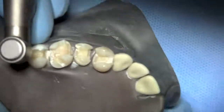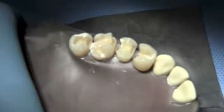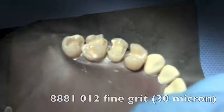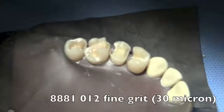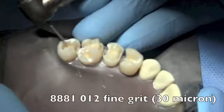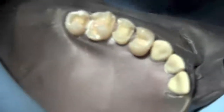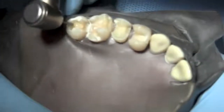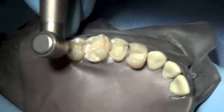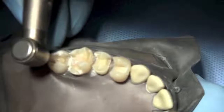The first thing we're going to do is we're just going to smooth this transition over here. And I think for this particular application, I'm going to use an 88012, which is the same burr in shape, but it's a finer grit. So it uses a 30 micron grit burr rather than a much more coarse grit. And so we're going to just use this burr to go ahead and round off that sharp area right there. Didn't take much effort.